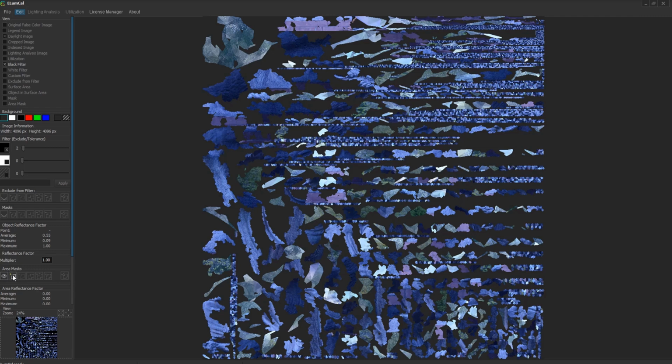Knowing the average reflectance of any area, we should check if software calculates the same value. Let's say it should be 0.27. It's not. So, we use the reflectance factor multiplier. The software will calculate the average, minimum and maximum reflection factors for the Frederick Chopin Monument.